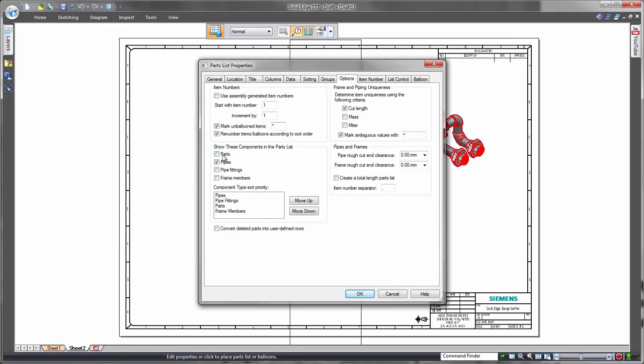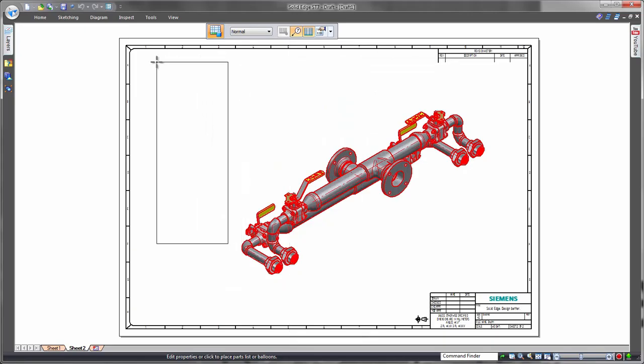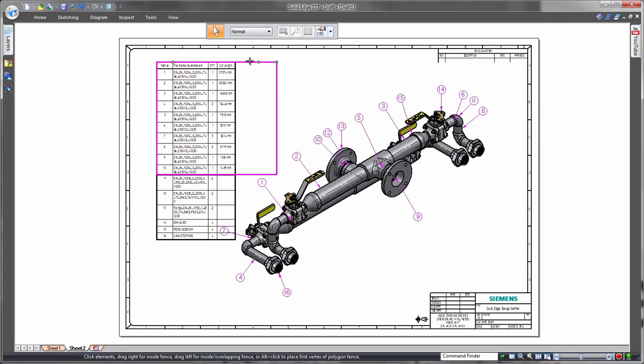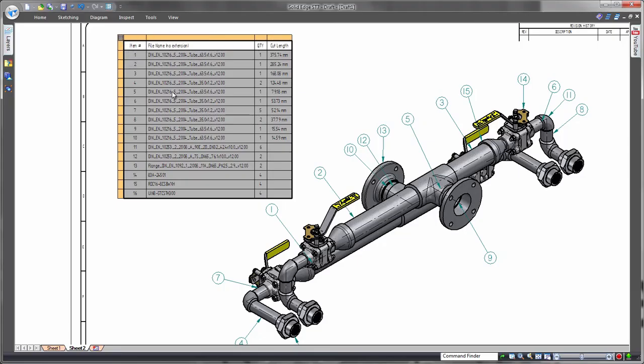Solid Edge automates access of design lengths, making them available for placement into a table. Because it's fully dependent on any 3D design changes, this tabular information stays up to date. This intelligent table provides some handy reference back to the assembly, as components highlight in the view as they're selected, and component thumbnails can be quickly referenced.